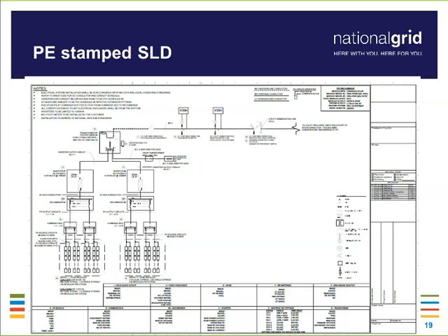As we travel down the single line here, we are showing the utility metering. That is also required. It is something you would need to show. Now on this specific drawing, they are showing customer metering. That would not be necessary for us to see, but if it's part of your design and you want to have one package for submission to us, and it's the same package to submit to construction, and you want that installed with the construction contract, that's totally fine that you show it. But it is not required for National Grid to see the customer metering that's shown on this illustration.